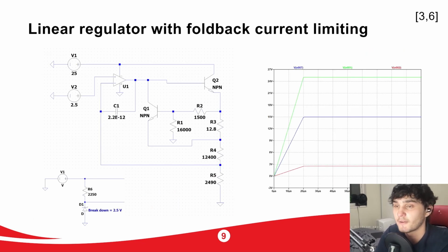The low noise amplifiers, switches, and frequency synthesizers have voltage and current limits. To ensure that the currents are in safe use, I will use a linear regulator with feedback current limiting circuits that use NPN transistors, op amps, and Zener diodes. This design showcases the LNA circuit I created in LTspice.